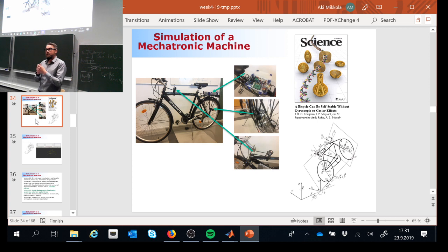We're measuring quantities that are easy to measure: steering angle, leaning angle, and forward velocity. This information comes into the model. The model uses kinematic analysis to get the full picture of the bicycle state, and using post-processing procedures, it makes an estimation of the forces imposed on the bicycle. So the input is a simple measurement. The output is forces that are very difficult to measure.